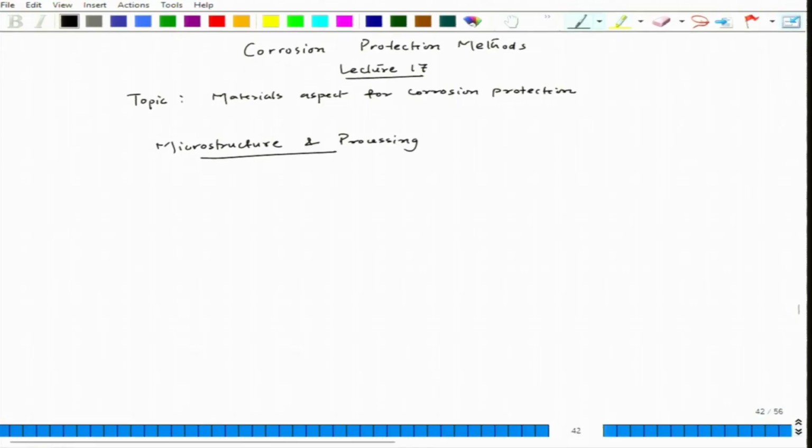When we talk about grained, the grain size would also matter. That grain size variation could be from fine grain, to a mixture of fine and coarse grain, to a very coarse grain, and when we talk about amorphous, there is no grain. There is one more aspect, which is single grain, meaning there are no grain boundaries except the boundary between the environment and the material.